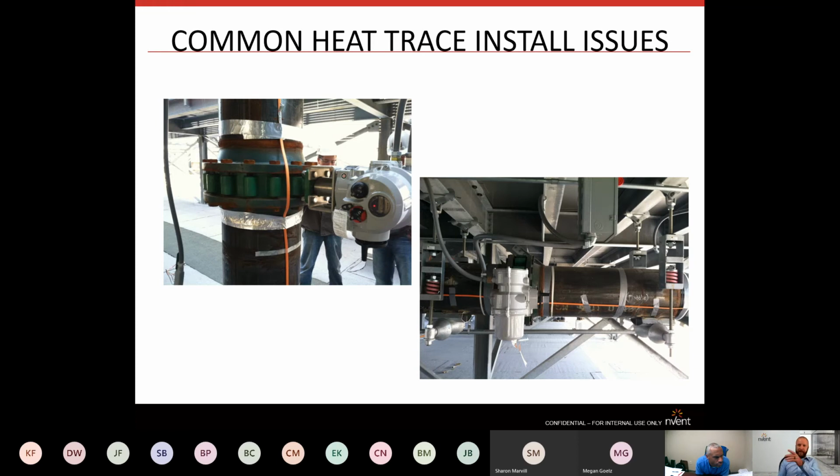I can tell you right now that application right there with that cable going over that valve will freeze up in any normal application in one winter. You have to put a wrap of X amount of feet, and I'm saying X because it depends on the temperature that you want to maintain, the size of it, the minimum ambient, all that stuff. But it wouldn't be uncommon to look at a valve that size and say that it needs 6 to 7 feet of cable as opposed to that straight run of maybe 6 or 7 inches. So that's a typical mishap, in that people will go right past those additional items within that pipe and then wonder why there's a freeze up.